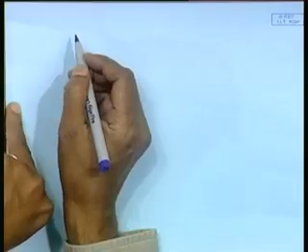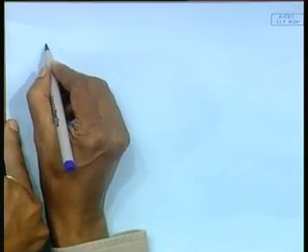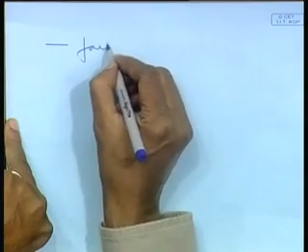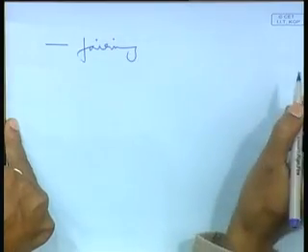So, getting rid of it could be by two ways. One is, well, let it happen and then do fairing. By fairing, I mean deformation has taken place, now you have to try to straighten it, right. Obviously, that is not a very good way of doing things, because you do additional work once welding is done, and then you implement fairing techniques such that you negate those deformations.